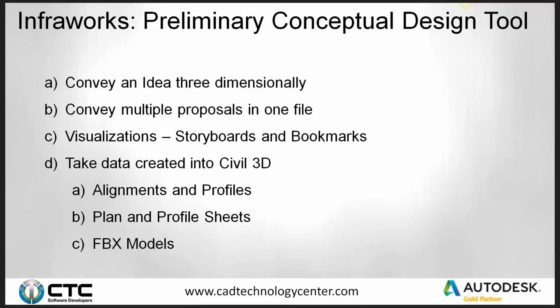And then finally our FBX or solid models. I like bringing in an FBX model because it ends up being like the overall existing surface or the finished proposed surface, and I can use that model for vehicle tracking. I like driving my road in there, so if I have a two-lane road widening out to 4, can my semi-truck make it through that widening? If my road curves, can my semi-truck still take that corner, and how fast can it take that corner?